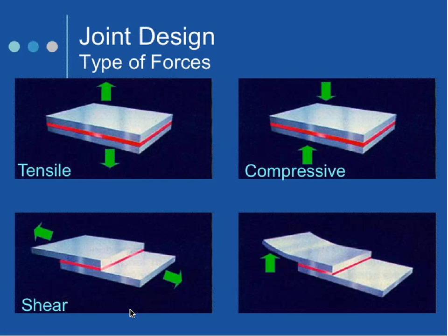Shear force looks a little different. You have an overlap and it's a sliding motion. I always think of earthquakes because I'm in earthquake country. I'm in southern, you're in northern California. It's that sliding motion over the surface. And actually, shear forces are how we measure the strength of adhesives. We'll put your bonded assembly in an Instron and pull in opposite directions and measure the pound pull force on that particular device. Peel, as you can see over the very edge, and cleavage, a little bit different.